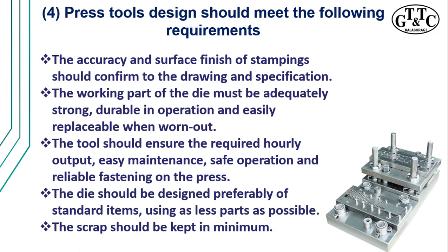The second point is the working tool parts should be strong enough and durable enough in operation and should be easily replaced when they are worn out or damaged. The third one is the tool should perform at a specific production rate, that is the components produced per hour, with easy maintenance and safe to perform.